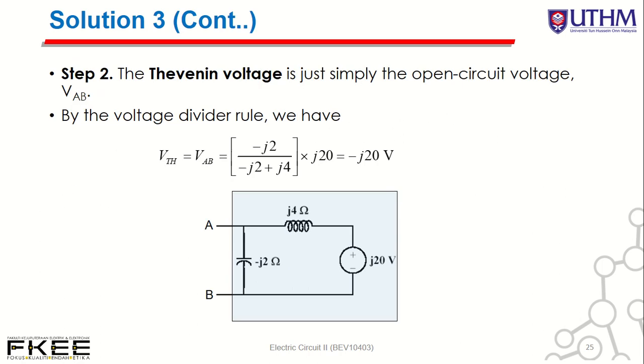Number 2, you can determine the Thevenin voltage. How to determine the Thevenin voltage? It is simply the open circuit voltage, basically equal to VAB. What is the value of VAB? You can solve by using voltage divider.